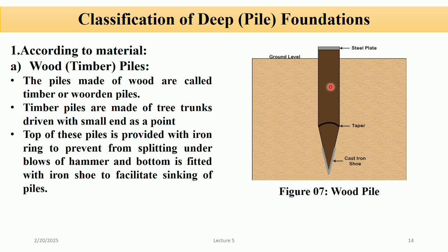So wooden piles are lightweight and easy to handle, cost effective, good for waterlogged areas, and environmentally friendly. But we should not use wood piles when there are heavy structures, and they need proper treatment to avoid rot, and are typically used for shallow to medium depth.